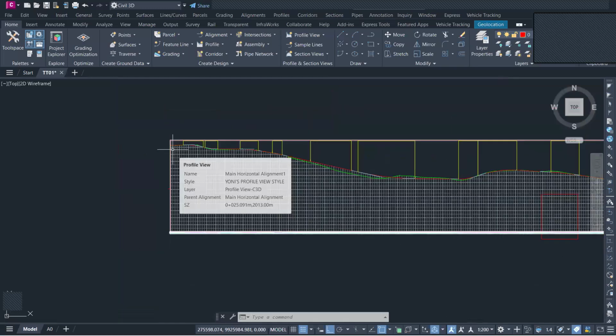Now, the next thing we need to do, we want to think about the second scenario. So the second scenario is where, from our geotechnical report, we have known that all of this material is cut to spoil. So we need to excavate 300 mm and cut it and throw it away. And then once we throw it away, we need to bring new materials to that specific site. It can be quite something.